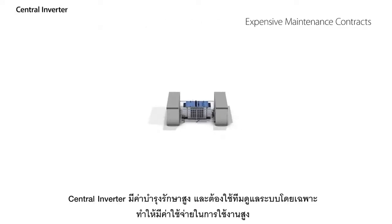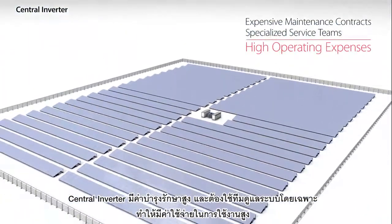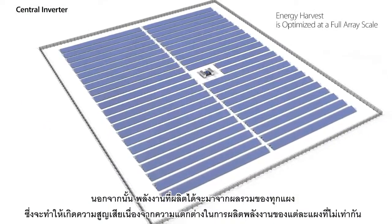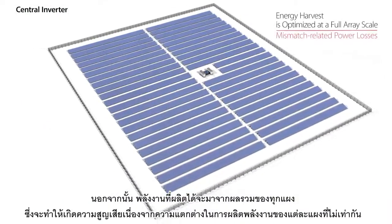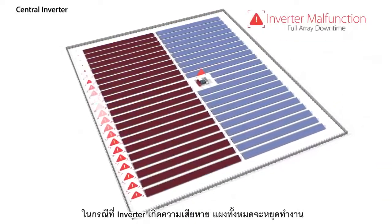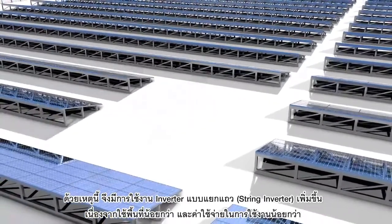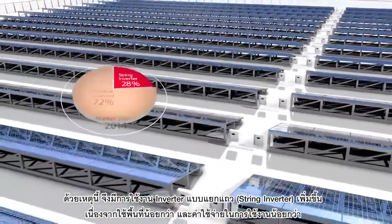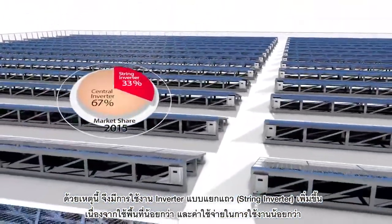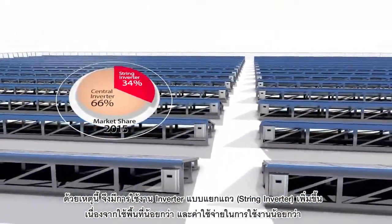Let's first take a look at central inverters. Central inverters have expensive maintenance contracts and can only be serviced by specialized teams. This leads to high operating expenses. In addition, energy harvest is optimized at a full array scale, leading to mismatch-related power losses, and every inverter malfunction results in full array downtime. For these reasons, decentralized architecture that uses multiple string inverters instead of central inverters is gaining market share. String inverter topology allows higher system availability, lower land use, and lower operation and maintenance expenses.